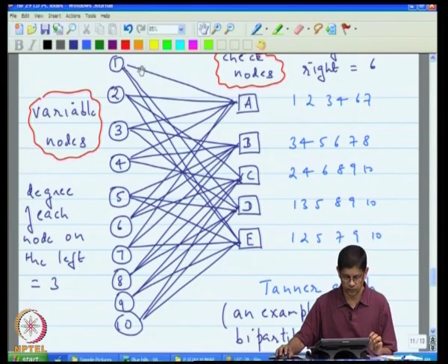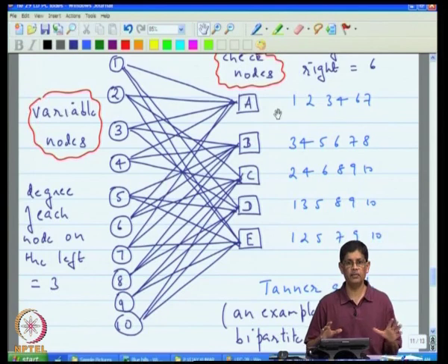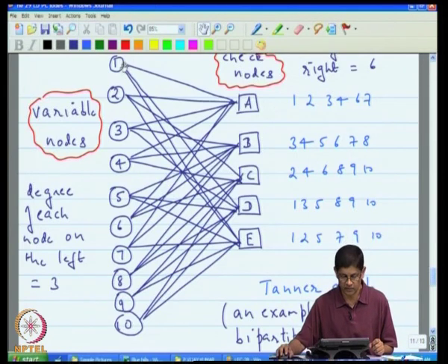Now, since the degree is fixed, it is a small number like 3 or 6, and typically in LDPC codes, when we talk about dv-dc regular codes, the block length could be very large, but we will still fix these degrees. So, what that means is that the number of ones in the matrix is automatically some multiple of n. So, it is order of n. For this reason, these are called LDPC codes.